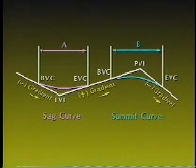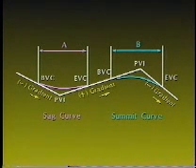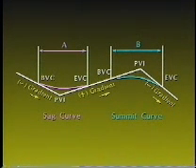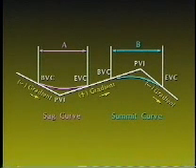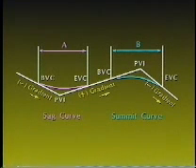This graphic shows the two classifications of vertical curves. Curve A points upwards from its point of beginning, or BVC, and is called a sag curve. Curve B moves downwards from its point of beginning, or BVC, and is called a summit or crest curve.